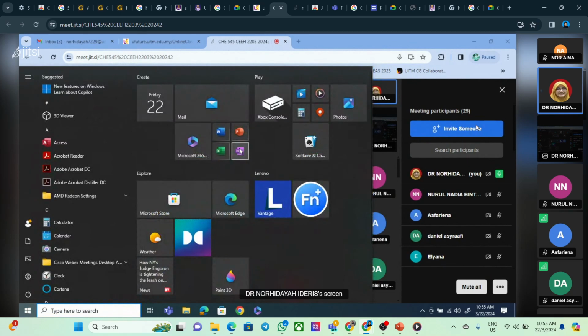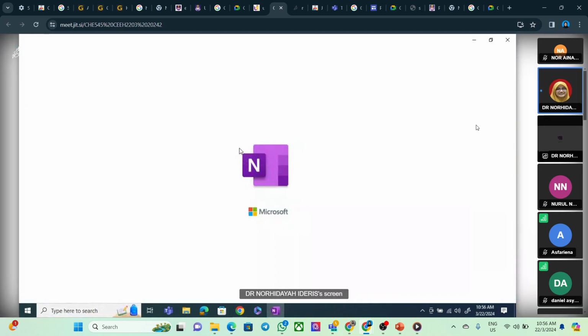Alright. So the equation that we're going to use is the NA1, inside the blue box. NA1 is DAB P A1 minus P A2 over R T R1 PBM. So the values of R, T and R1 are known, and DAB, PA1, PA2 are known. The only thing that we don't know is the PBM.